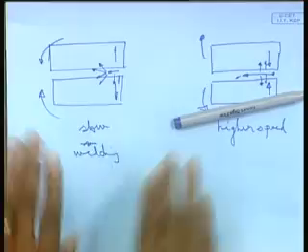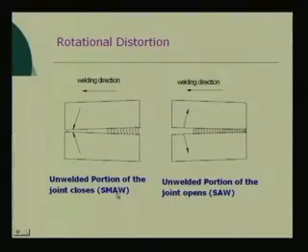So, balancing that will cause a moment to rotate it outwards, whereas in the slow welding process, the weld speed is slow. Generally, SMAW means manual welding, right. Here I have mentioned SMAW, shielded metal arc welding, it is a manual welding, and here I have mentioned submerged arc welding, that is an automated welding. So, I can go for a higher speed.